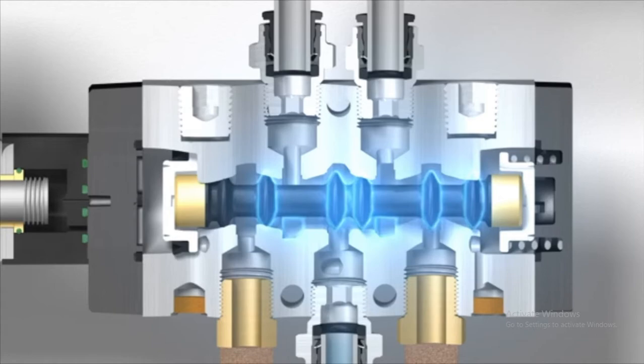turned on. In most automated equipment, a PLC, or programmable logic controller, will instruct the valve to shift using an electrical signal. When the signal arrives at a portion of the valve called a solenoid coil, a magnetic field is created that pulls a cylindrical piece called a plunger towards it. When that plunger is unseated, it allows air from inside the valve, known as pilot pressure, to push the spool to the right.